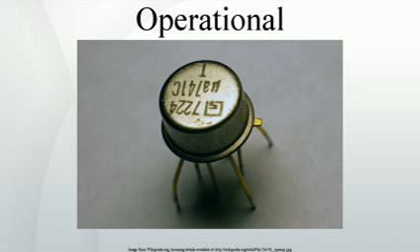Note that the non-inverting input of the operational amplifier will need a path for DC to ground. If the signal source might not give this, or if that source requires a given load impedance, the circuit will require another resistor, from input to ground. In either case, the ideal value for the feedback resistors, to give minimum offset voltage, will be such that the two resistances in parallel roughly equal the resistance to ground at the non-inverting input pin.